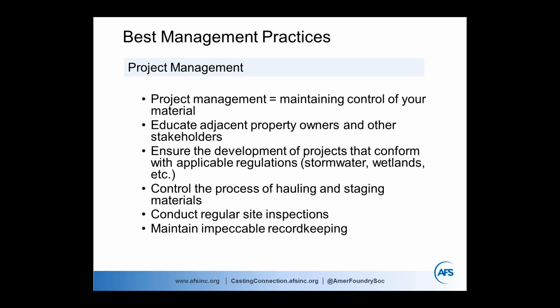Just ensuring that any equipment that's being used to handle material between your facility and the end use is all in good condition. Trucks aren't being overloaded. Tarps are in good condition so you don't have dusting on the road. Make sure you want that site to have regular site inspections, whether it's weekly or whatever it is, so you can ensure that there's an adequacy of stormwater controls and water control and dust generation. Maybe you need a tracking pad to keep any tracking off the road. All of this stuff is crucial, and also, ultimately, all the due diligence and everything you're doing and your results, keep good records of all that, and basically what material is going into what projects.